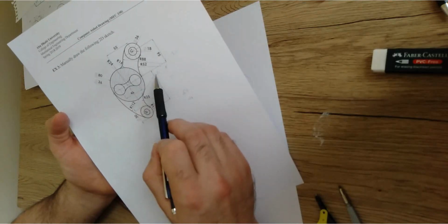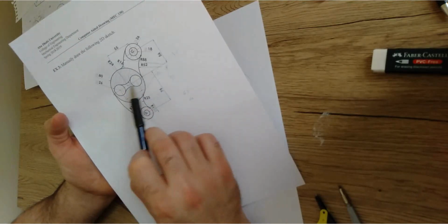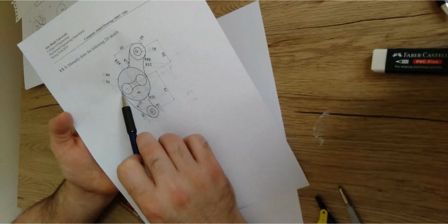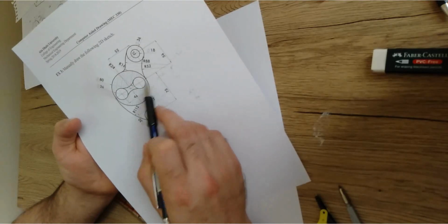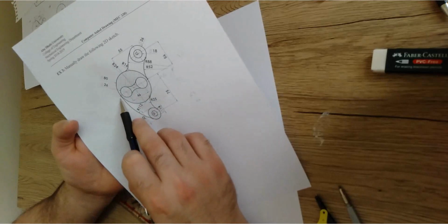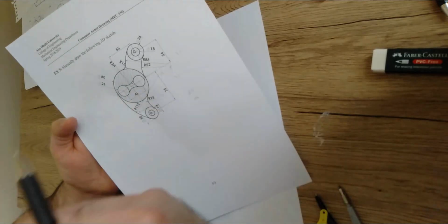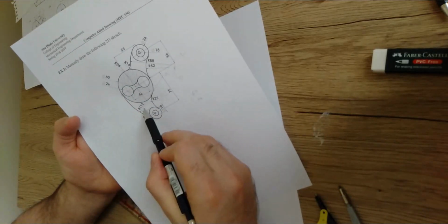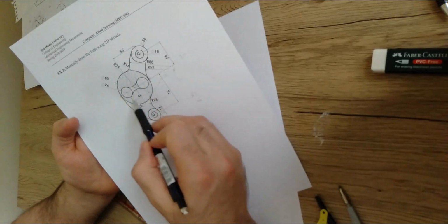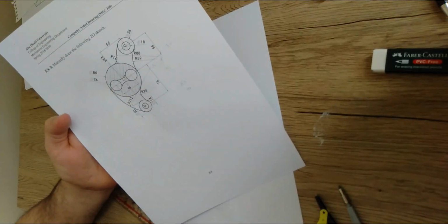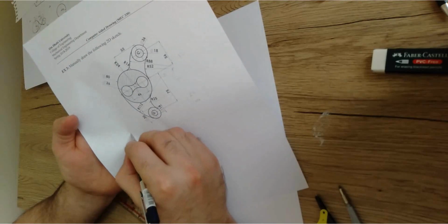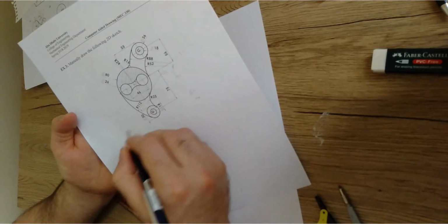Then if I ask you to move from the center to the center, are you going to go over the tangent point, this one? No. You're just going to move directly from the center to the center without passing over the tangent points. It means that we have to subtract: 112 minus 40, which is the radius of the big circle. This gives us 60 plus 12, which is 72. It means that we have to open from the big circle by 72.